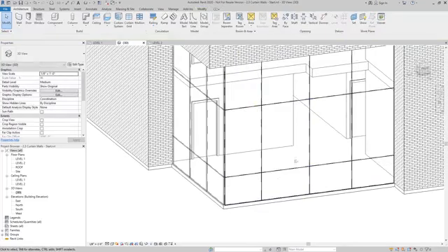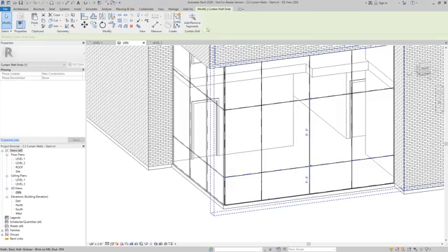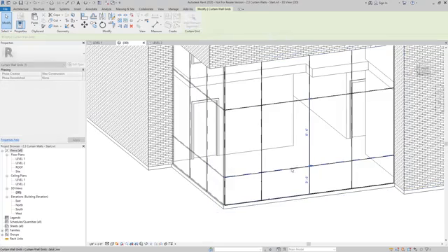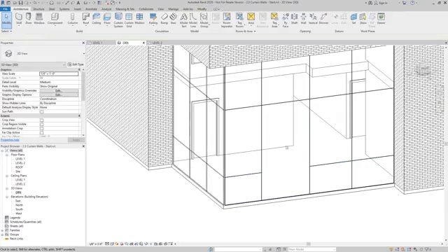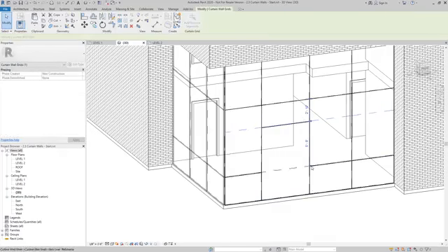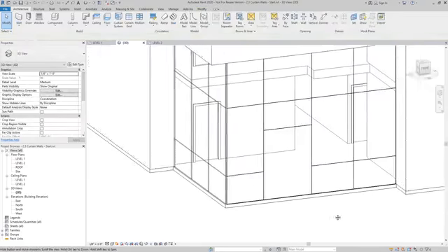To create the panel for our door, what I'll use is the Add Remove Segments option. So first thing, I'll select a curtain wall grid, and then pick Add Remove Segments, and select the segment I want to remove. I can do the same thing when creating a curtain grid. Instead of using the All Segments option, which is what we have been using, I can change it to One Segment, which will only show one of the segments within here. This grid, I'm going to set to be 8'8" to create the panel for the door.